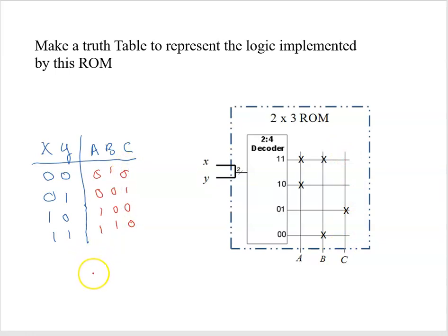So now we can say A is just equal to X, and again let's do our S1 and S0 the way these are going in. A is just equal to X, B is equal to X exclusive OR Y prime, it's the equivalence function, and C is just equal to, what is C equal to? C is equal to X not Y.